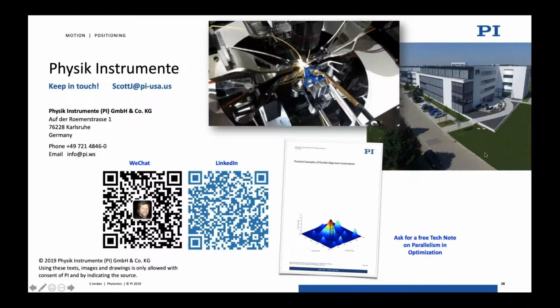Are there services one can purchase for small fiber component alignment in the 2.8 to 4.8 micron wavelength? And the answer is, yeah, we just need fast metrology. That could be a problem for those longer wavelengths because they use thermopile detectors that can be slow.